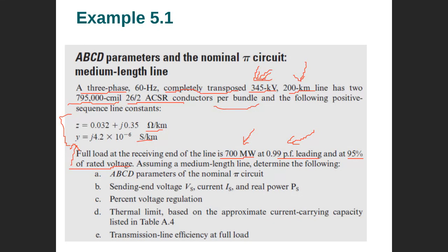So this will be P minus jQ, not P plus jQ, P minus jQ. So if you're asked to find the reactive power, then you can determine it is minus jQ. So the load does not absorb reactive power. The load injects reactive power, or the load delivers reactive power.